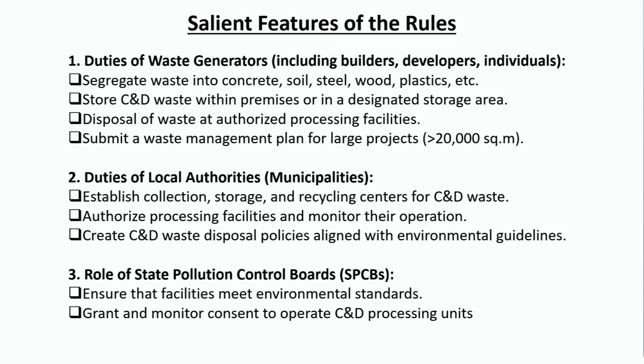The first is duties of waste generators, including builders, developers and individuals. Their duty is to segregate waste into concrete, soil, steel, plastic, wood, etc., to store construction and demolition waste within the premises or in a designated storage area, dispose of waste at authorized processing facilities, and submit a waste management plan for large projects, especially for more than 20,000 square meters.